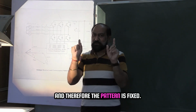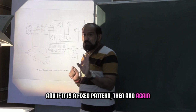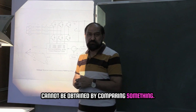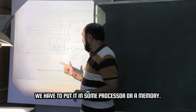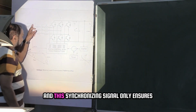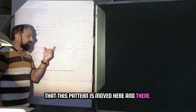The pattern is therefore fixed, and the position of the pulses cannot be obtained by comparing something. We have to put it in some processor or memory, and that's why you have a digital control with a fixed PWM pattern. And this synchronizing signal only ensures that this pattern is moved here and there.